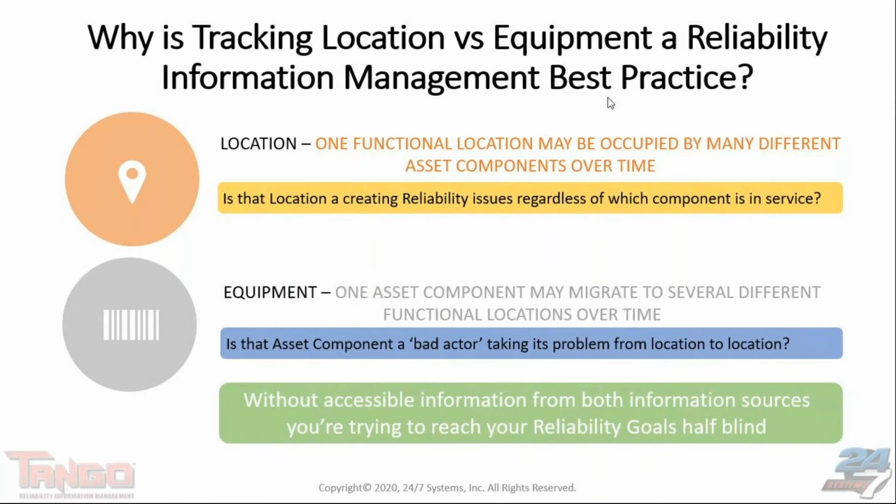And you can be very accurate in understanding condition without knowing a whole lot. Of course, the more you know about the individual details of that motor, the bearings that are in it, the more accurate your analysis can be. But you can do that against the location, the base plate location. By comparison, equipment in my nomenclature is where I'm talking about a unique individual, a unique tag numbered or serial numbered motor, pump, or gearbox that might be in one location on one base plate today.